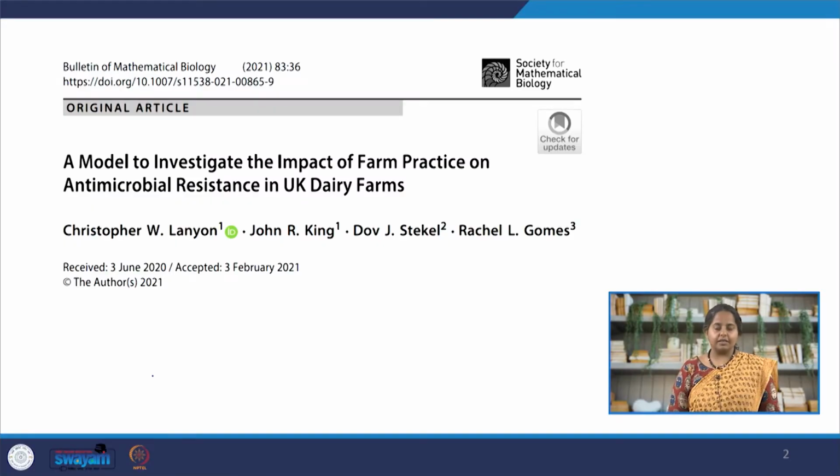We talked about the assumptions, and the basic theory that we already know prior to modeling, of how antimicrobial resistance spreads from a sensitive microbe to a resistant microbe in a complex system like a slurry tank. We did this in the previous lecture. In today's lecture, we are going to write the empirical model. Briefly, it's just going to be a mass balance that accounts for incoming slurry, outgoing slurry, and any kind of reaction happening inside the tank.